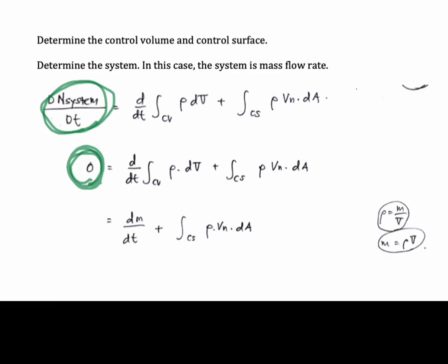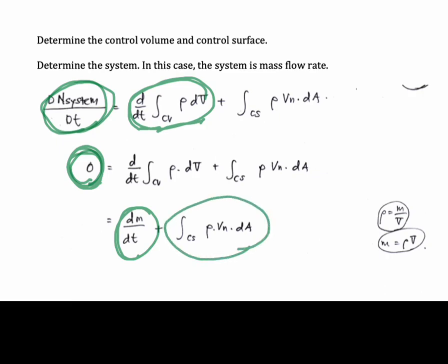And then for the first term on the right here, you will get the dm/dt. The dm/dt here means the increment of mass according to time for a certain area of our control volume. And then we have the integration of rho v dA, which means the changes of something on the surface.